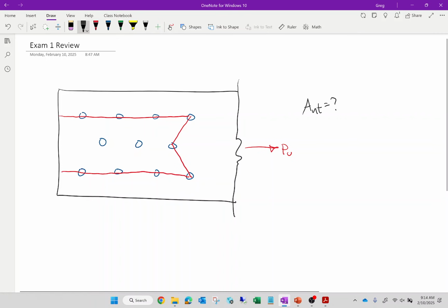The net area in shear is going to be the gross area in shear minus 1, 2, 3.5. But, hold on, if this is my failure block, whatever the gross area in shear and the net area in shear is, I have to double it because there's a path up there too. Does everybody see that? Everybody okay with that? Okay. So the way I would do this is I would say this equals the gross area, and I'm just going to use that length.